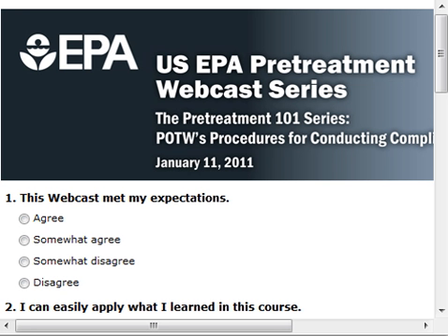And last but not least, you might have an industry that is discharging pollutants that you know or have experienced has caused problems at your POTW. In order to prevent such problems, you can call a facility that discharges less than 25,000 gallons, less than 5%, but is giving you significant pollutants that you know either can cause or have historically caused a problem at your POTW, a significant industrial user.